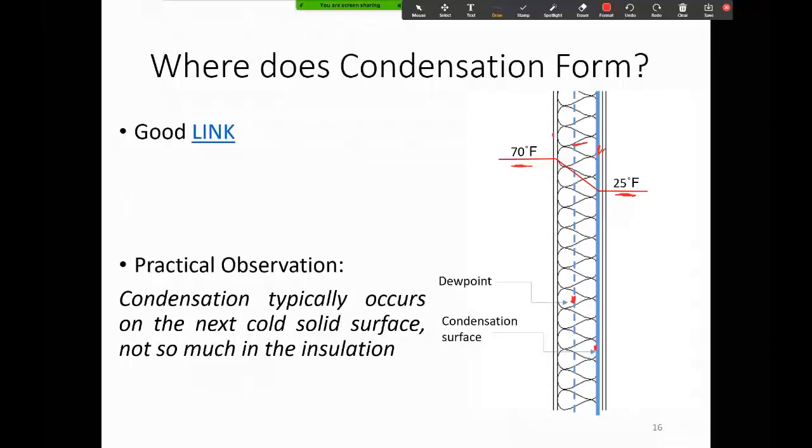And remember, in psychrometrics, every 18 or 20 degrees doubles the amount of moisture that the air can hold. So, if you've got a leak on the exterior and a leak on the interior, air is going to find its way through somehow. Higher pressures inside relative to outside, higher moisture content, higher relative humidity. So at some point, you're going to hit the dew point temperature. And remember, the dew point temperature could be right here, but it's not going to condense until it hits that cold surface.